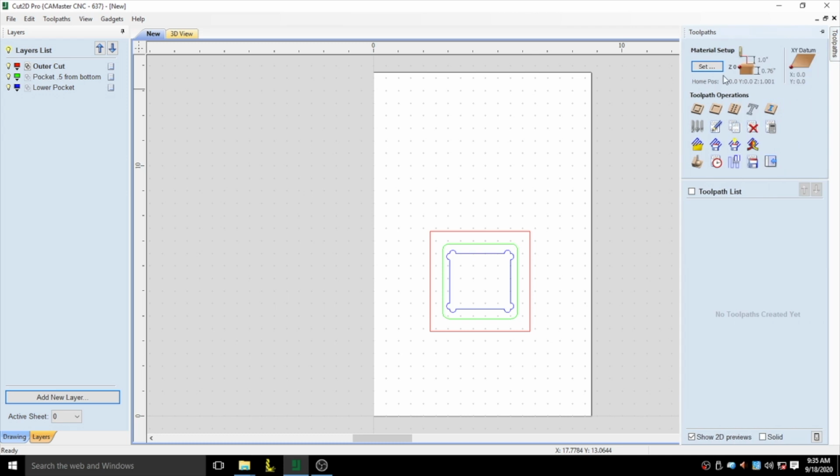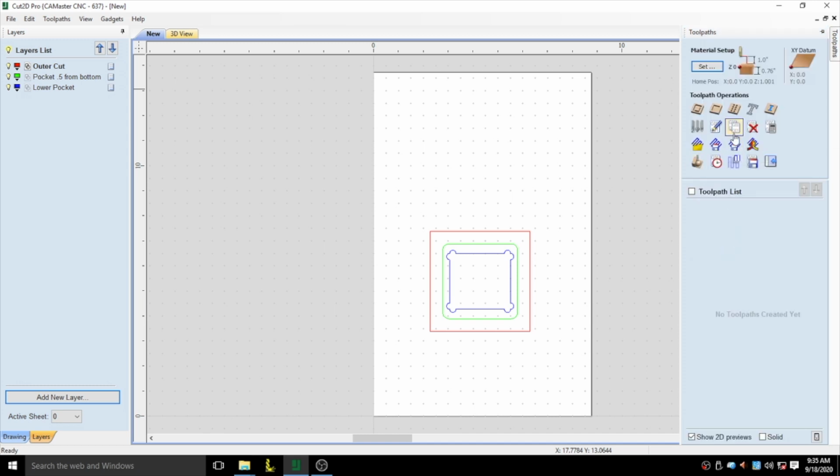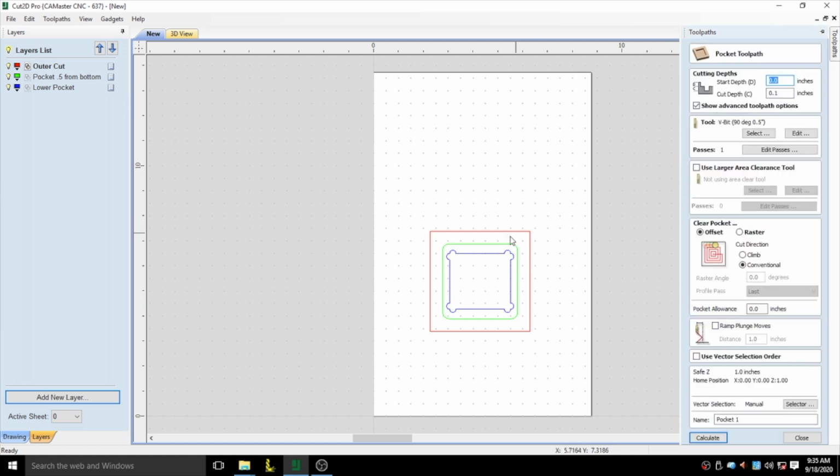So what we're going to do right now, I just open the Toolpaths menu up here, and you can see some information like the height of the material, how tall that cutter is going to be. We can edit our stock material again if we want to. And for the clearance, we may want to change it at some point. The rest of this stuff, pretty decent. So let's hit OK. And down here, we can start generating some toolpaths, either a profile, so inner or outer on the line. We can do also like a pocket, and that's what we're going to work with right now.